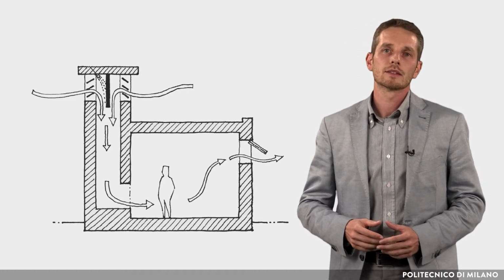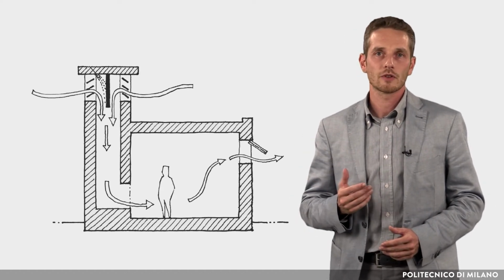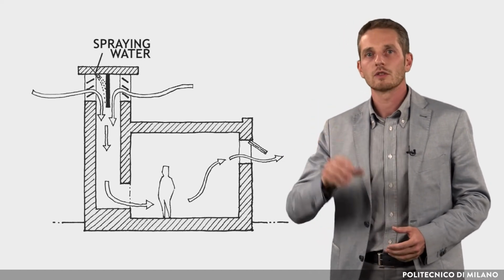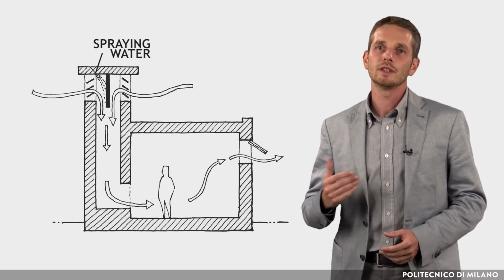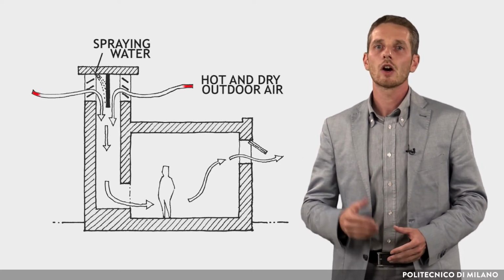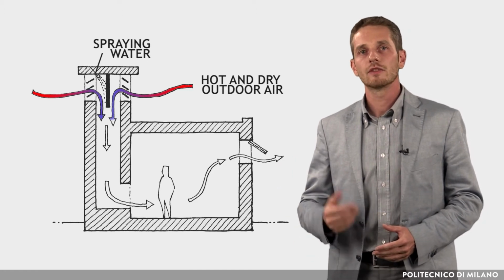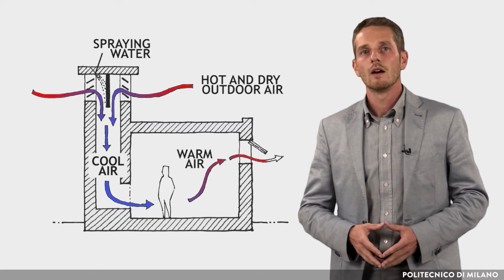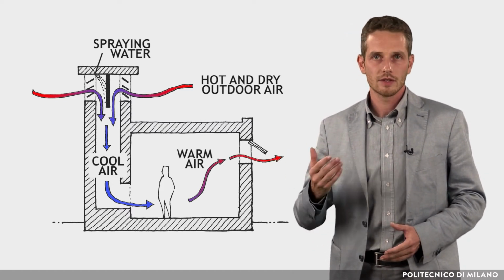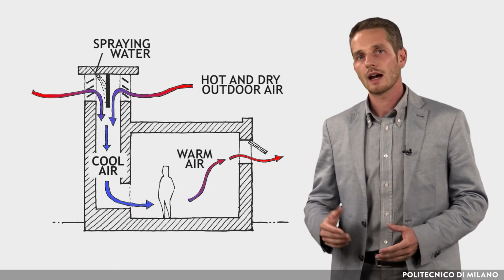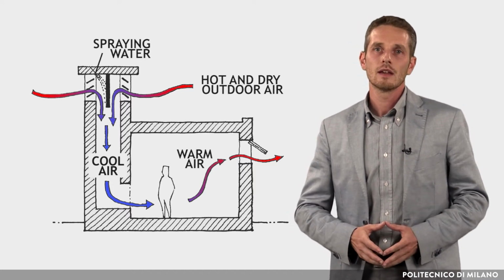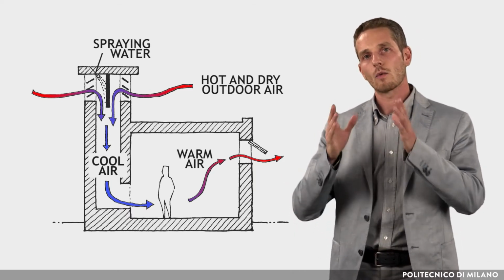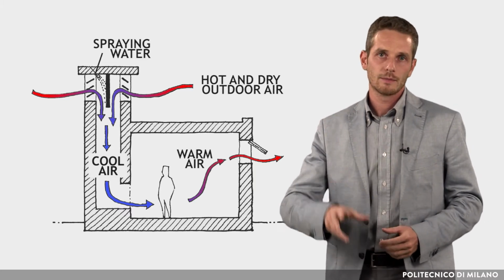In hot arid climates, the adiabatic humidification process, or evaporative cooling, is always effective. Spraying water into a stream of air cools and humidifies it. In very hot, dry climates, this physical phenomenon can be used to improve environmental comfort. One way to take advantage of this physical principle and at the same time to facilitate a good ventilation is to cool the air by adiabatic humidification in a tower and spread it into the space.